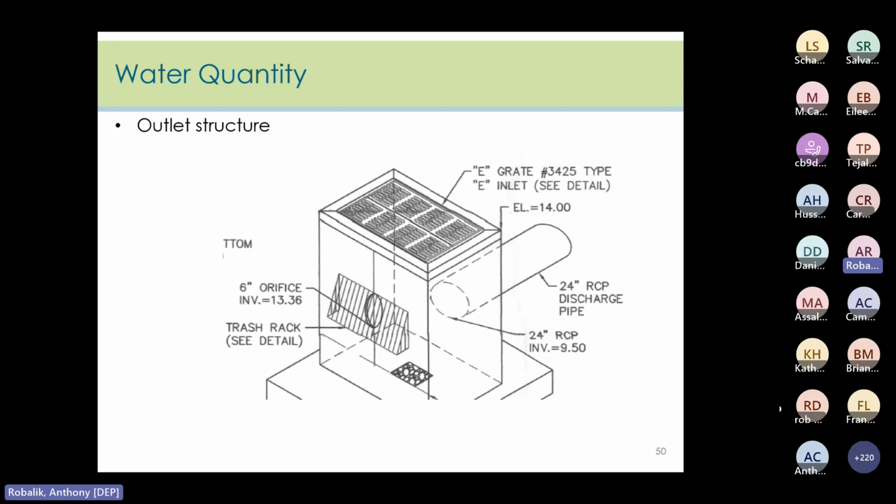It's not a huge problem because it's not a significant difference, but it's definitely a difference that's going to have to be accounted for before this is given a final approval. Most likely what happened is they probably raised this up for groundwater recharge reasons and just forgot to update that part of the model because groundwater recharge doesn't really play into that. So we're just going to have them fix the model to show that everything still works with this orifice being slightly higher.